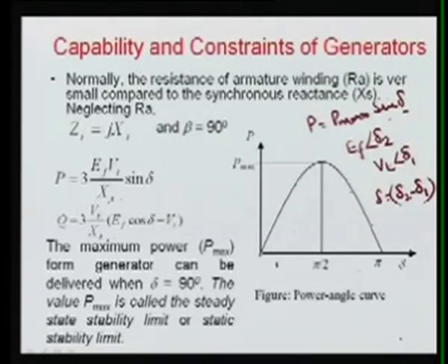So this is the voltage angle. Now again, you must be very careful: this delta is your load angle, however delta 2 and delta 1 are the voltage angles. Both are totally different. So the difference of the voltage angles is the load angle between two adjacent buses. If a system or element is connected between two buses, then the difference of their voltage angles is the load angle.